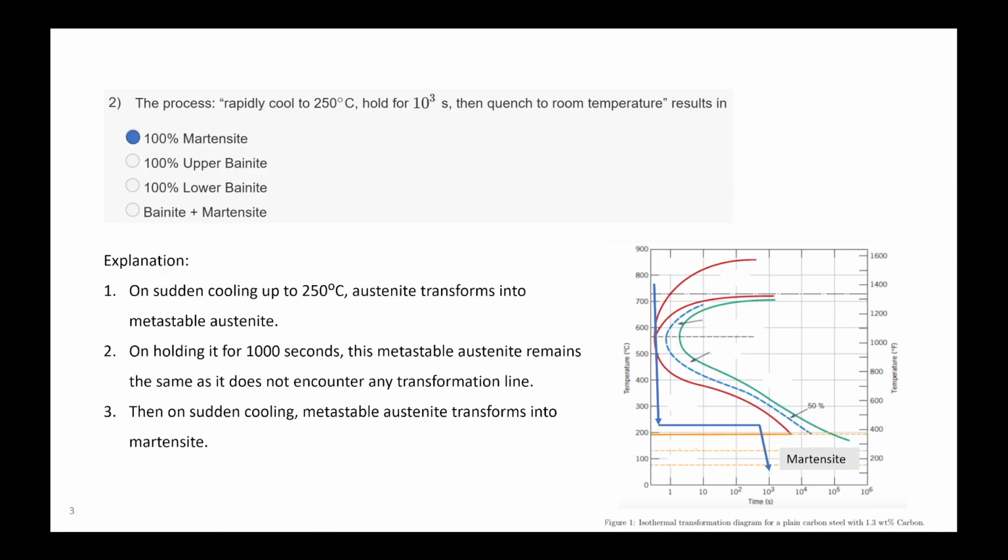Ma'am, what do you mean by this homogeneous deformation? The word homogeneous means it will be the same in a particular direction. So it was asking about that necking portion, whether the deformation is homogeneous or not. After necking, it is not homogeneous.